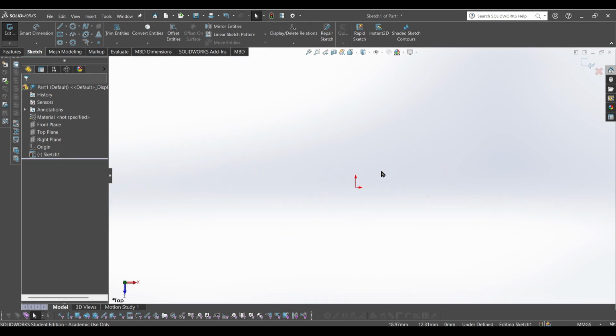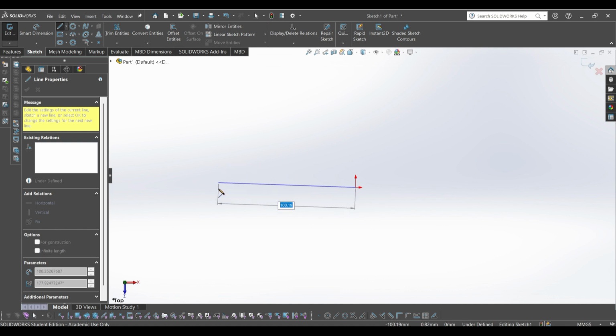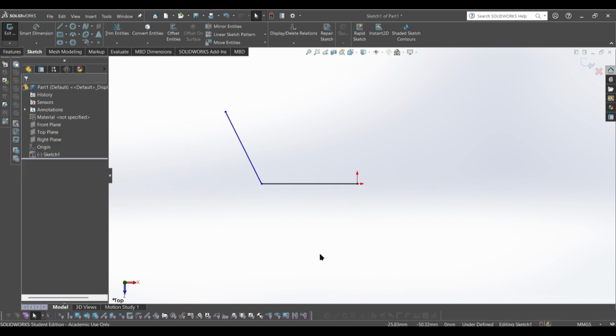When we're CADing in FTC, we want to do this thing called defining our sketches. In SOLIDWORKS, you can have undefined sketches. It's not going to give you an error message or anything. But when you're CADing for something like an FTC part, you want to define your sketches so everything is accurate and has the correct measurements. When something is undefined, it means that it's kind of just there. It doesn't have any specific measurements or relations or properties assigned to it. So for example, this sketch would be undefined.